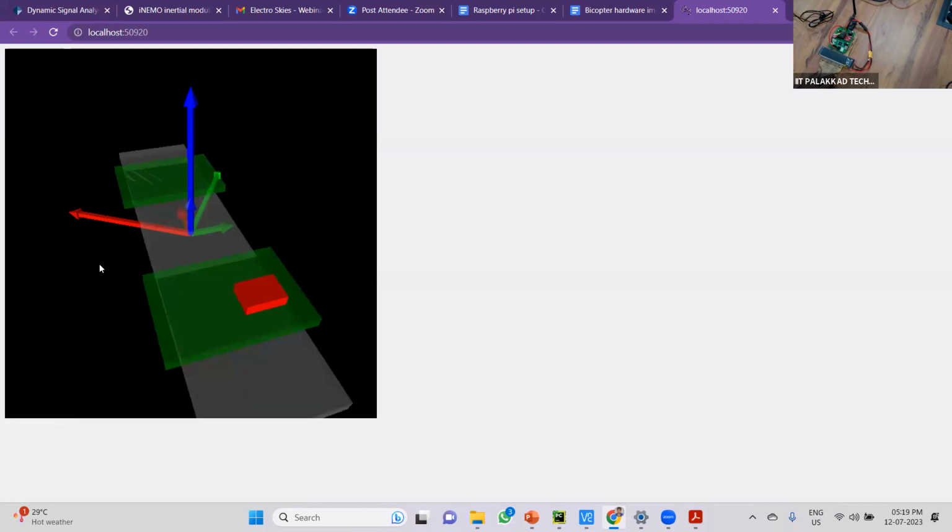But if I keep it on the ground, for example, you can see only the vibrations, right? It's giving vibrations. That means the accelerometer is picking up the noise, even small noise also. It's picking noise and giving vibrations. That means the drone is vibrating, right? You can't keep this type of vibrating sensor there. It will vibrate and will go and hit somewhere, right?